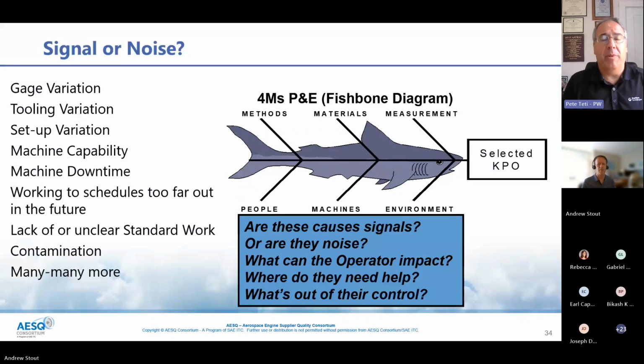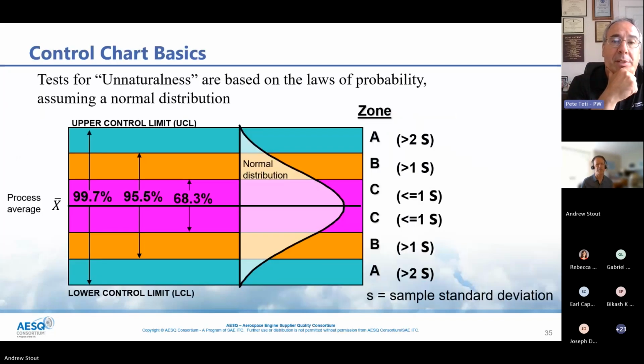And so it's important when we think about MSA, there are two ratios we look at, percent to tolerance and percent to study variation. It's that percent to study variation we want to be less than 30%, and that will tell us that the control charts will be useful. They will help identify when a key input is going out of control and we can take action on it. So that's an important interaction between RM 13006 and RM 13003.